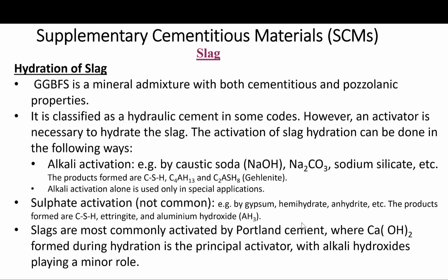So, how slag hydrates and how it works. Ground granulated blast furnace slag is a mineral admixture with both cementitious and pozzolanic properties, as I have been saying. It is classified as a hydraulic cement in some codes, so be aware of that. In that case, an activator is necessary to hydrate the slag. The activation of the slag hydration can be done in one of the following ways.